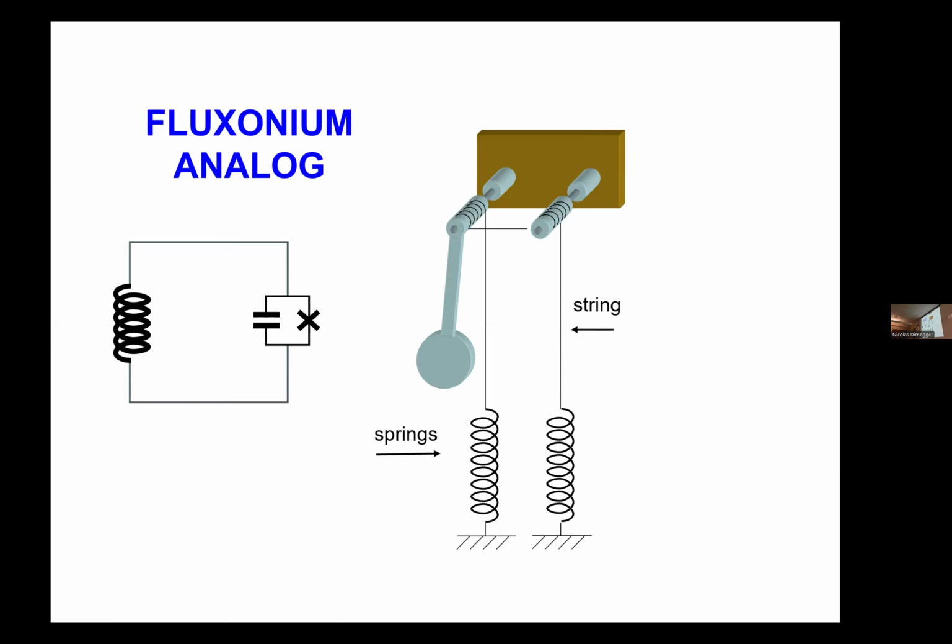And that means that you're leaving the representation where you say that this flux here is a phase variable that lives on a circle. And then by imagining that you have always this inductance, even a very, very large one, across your junction, you can go from this representation of the phase as a variable on a circle to a variable on a line.